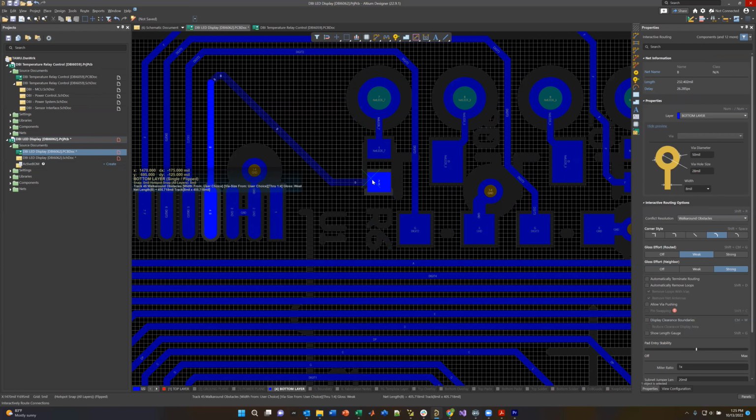So now that we've got that done, I have to change this. I also changed DC to DC converter stuff, so I technically need to reroute this a little bit. So effectively, what we have is this board here has this communications device, the RS-232 that we're talking about. It has basically this inductor and diode here. These two actually connect. This connects over here.